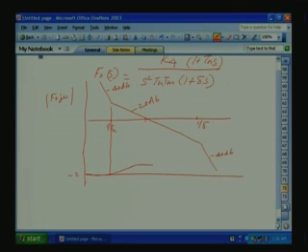Again the effect of the pole comes, and finally it goes down again. So we choose the Tn such that at this point we will have the maximum phase margin. This is called the phase margin. So we should have the maximum phase margin at this gain crossover.